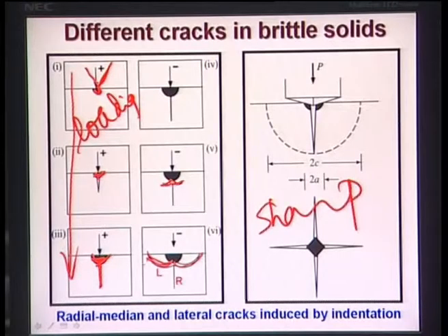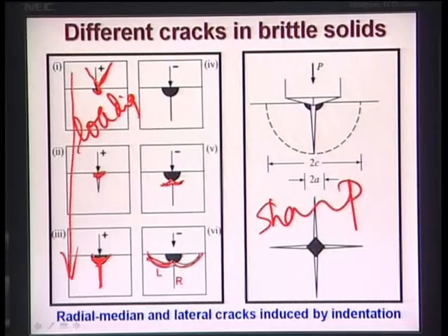Now what happens if you relate this kind of behavior to a friction and wear, or tribological, scenario? You can consider multiple sharp indentations going just like this. Once this lateral crack forms and touches the surface, the hatched region can be taken off from the surface, or can come out due to spalling of the material. Now the indenter goes like this and like this, in a to-and-fro motion. So what will happen?